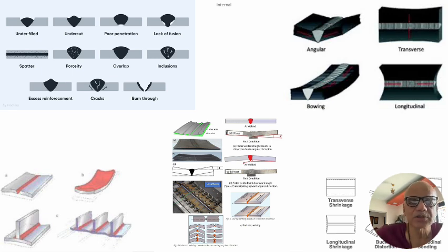And this is what happens if you happen to make a concave weld in a root run. If you try to give a concave weld, then the thickness at the center of the weld becomes very less. It cannot sustain and it fails or breaks and looks like a burn through or a crack in the root run or in the penetration. And these are all the defects which only by improving parameters and adjusting your angle of the torch or of the electrode you can improve.